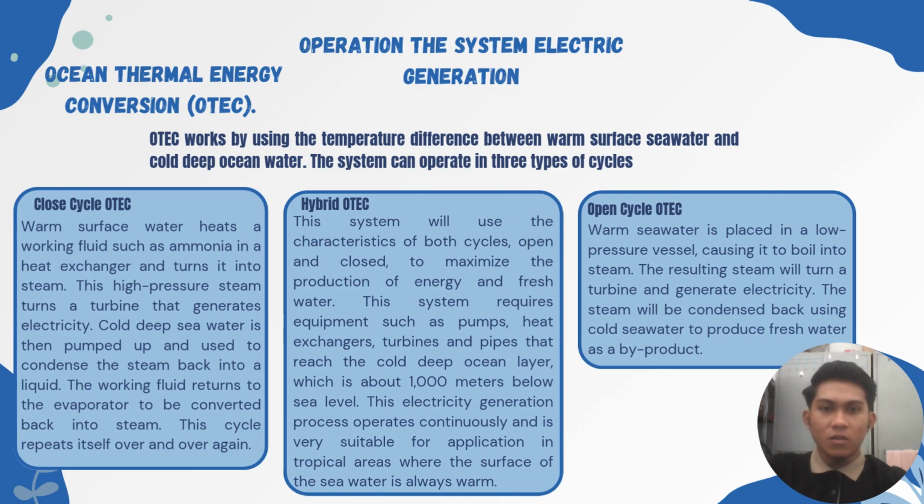And lastly is open cycle OTEC. Warm seawater is placed into a low-pressure vessel, causing it to boil into steam. The resulting steam will go to the turbine and generate electricity. The steam will be condensed back using cool seawater to produce fresh water as a byproduct.